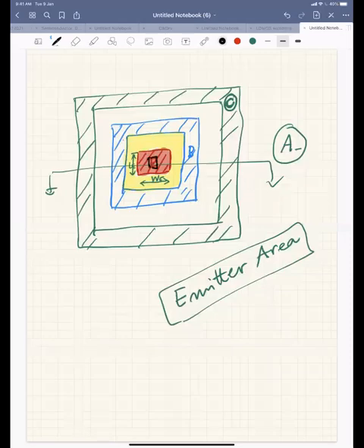You will have an emitter contact here, and the collector contact will also be distributed across this ring, and the emitter base contacts will also be distributed. So these are your contacts. You will see here also you have a mirror. If you take a cross section in the vertical or horizontal direction in the middle, these are mirror images. This is a symmetric transistor layout.